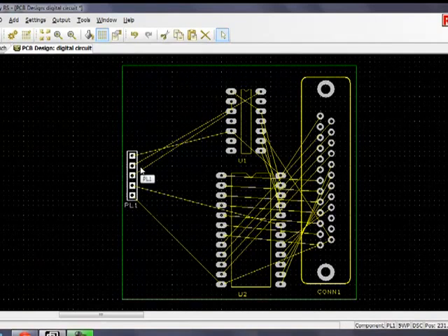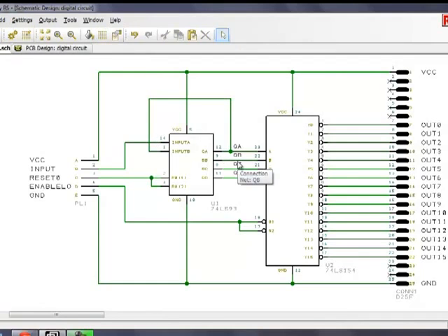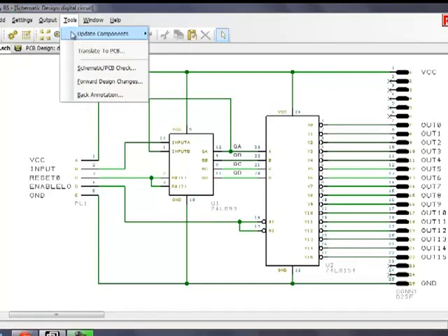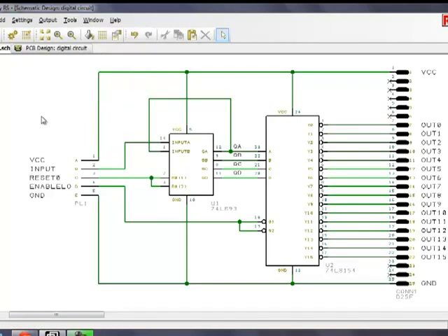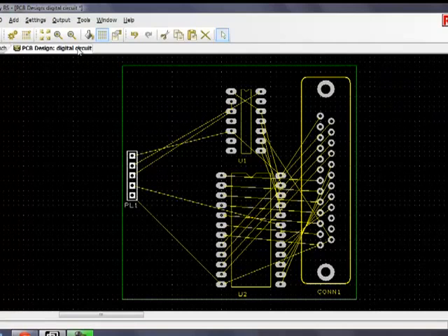What I like to think of as the intermediate phase before we move to a circuit board. From this point on, we could look to do auto routing, or we can simply do manual routing of this board. So just to summarise, what we've done this week is look at the schematic circuit here with the two digital devices and the plugs. We've used the Translate to PCB command. It took us through the wizard to set up the number of layers on the board, the size of the board, and how we wanted to deal with the components, and we ended up with this file.